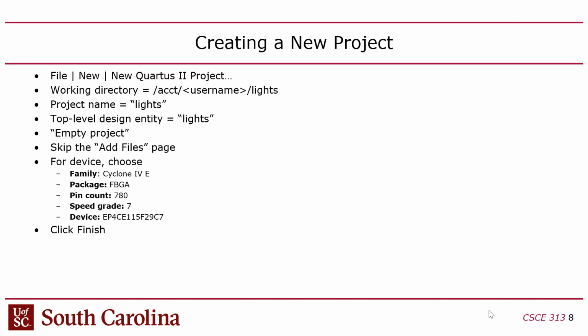And then you have to select the right FPGA. For some reason, there are 8 million different FPGAs that you can choose from. Unclear why. So you have to search a very long list to look up EP4CE115F29C7. 115 means 115,000 logic elements. EP4 means Cyclone 4, that's the generation of the FPGA. F29 refers to the package that it's in, that ceramic black thing you see on the circuit board. And C7 refers to the speed grade. Some FPGAs just work faster than others, and so they're grouped by speed grade.